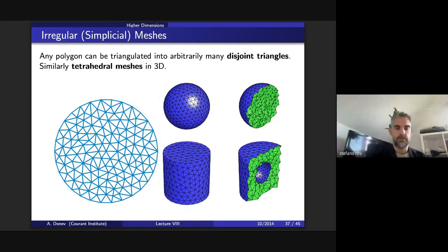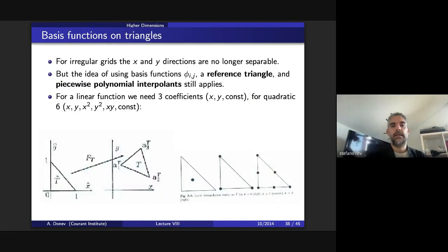So as we said, this was for the rectangular mesh. The rectangular mesh things are nice, but sometimes, again, this is very much a 3D graphics type of space, you can also mesh with disjoint triangles, or you can use a tetrahedral mesh, right? And then in that case, you can no longer use separable basis functions, because now you don't have this independence of the 2 directions. The 2 dimensions are together.